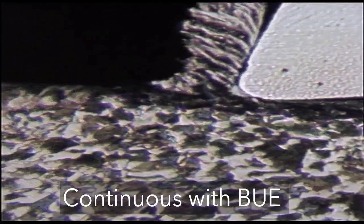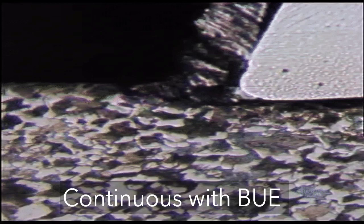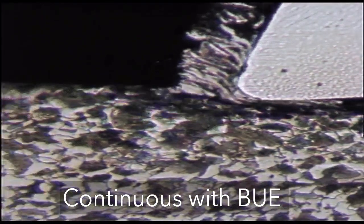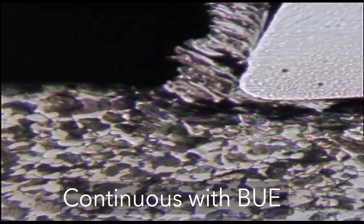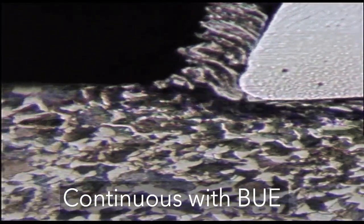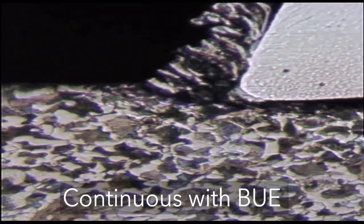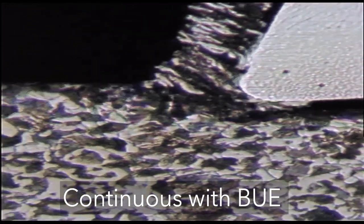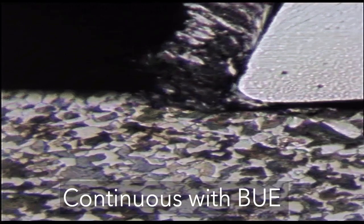When machining ductile materials at low to medium cutting speeds, friction between the tool and the chip will tend to cause a portion of the work material to adhere to the rake face of the tool near the cutting edge. This formation is called the built-up edge. The formation of the built-up edge is cyclic. It forms and grows, then becomes unstable and breaks off.